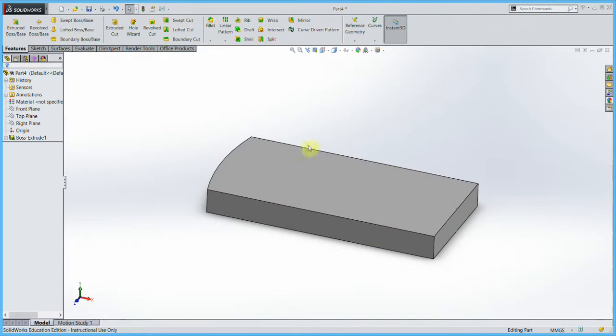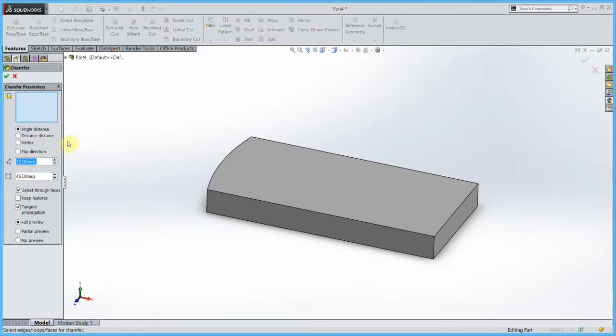So the next thing to do is we're going to put a couple of angle corners on here. They are called chamfers. So we click on this little arrow here and click on the word chamfer. They're going to be 2 millimeter chamfers, so put the word 2 in there and hit enter key.